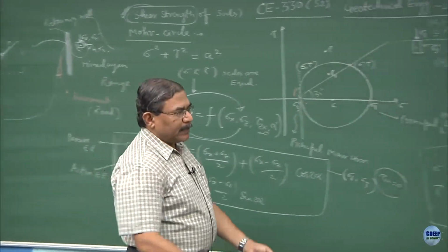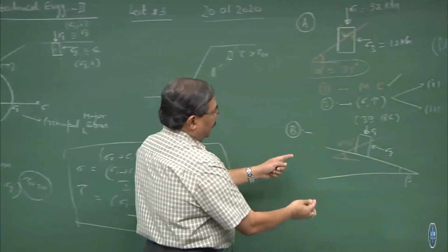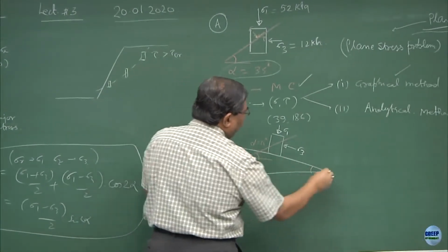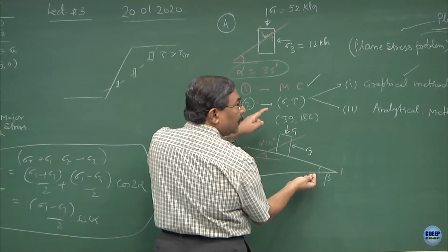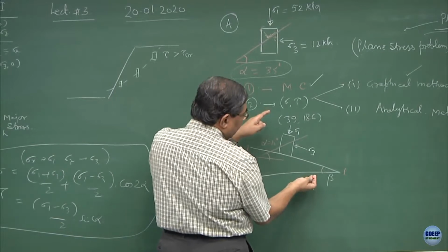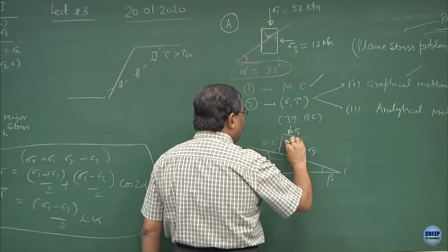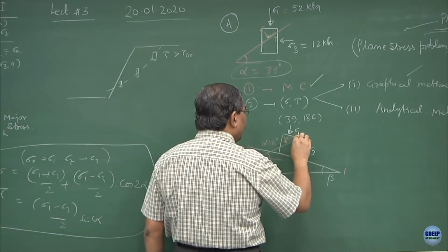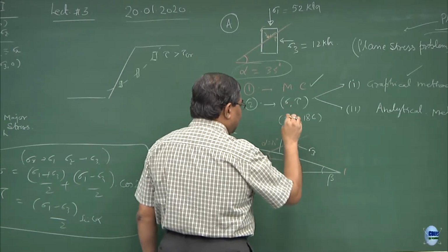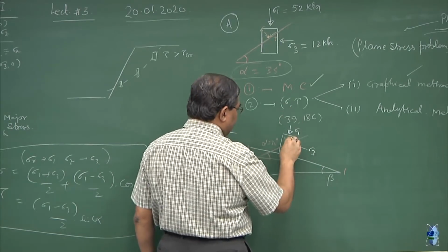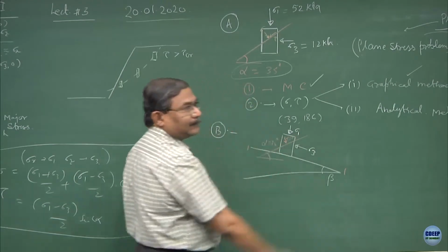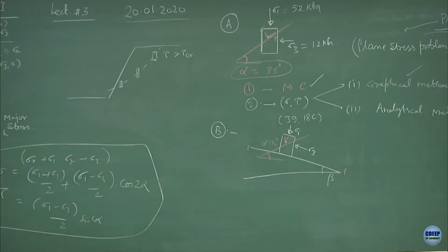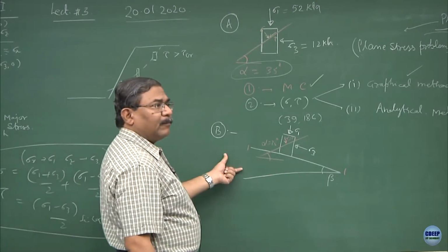This is what is known as axis rotation. This plane 1 1 has been rotated by an angle beta, and the question is whether tau sigma or sigma tau is going to be same or changed when I do the same analysis for 35-degree angle. Do you think something substantial is going to change or everything remains same?